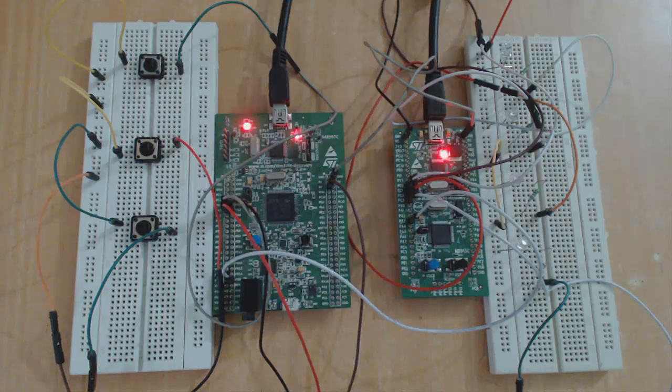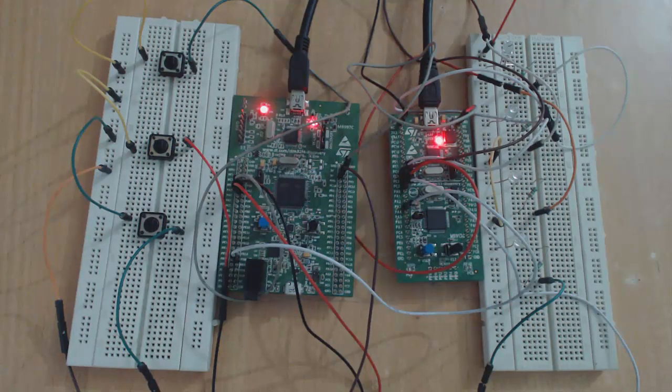Okay, now I will press this first switch. The moment I press this switch, it will generate an interrupt and it will send a character using UART communication through this wire, and then an interrupt will get generated on this second board. Now in this second board we have written the ISR to check what character we have received. So if we got a character, then this first LED will light up. So let's see.